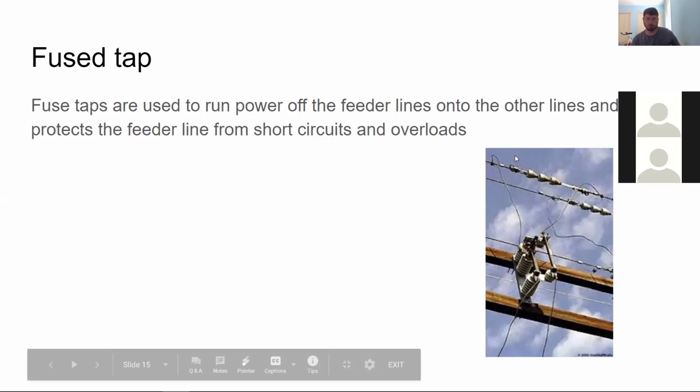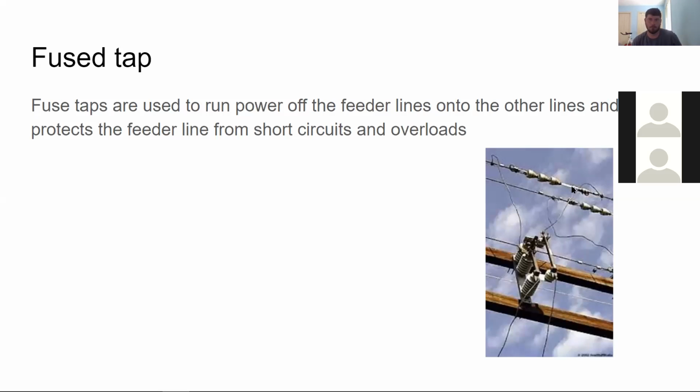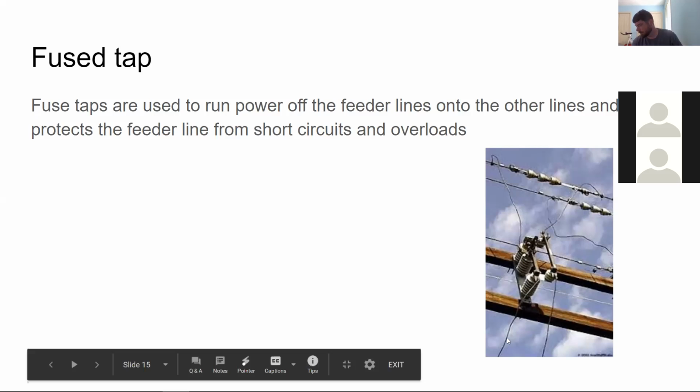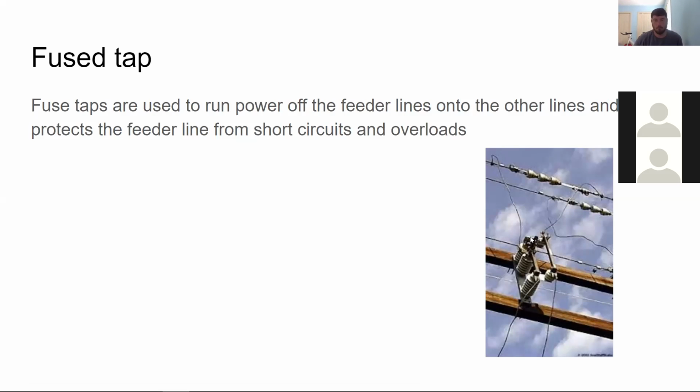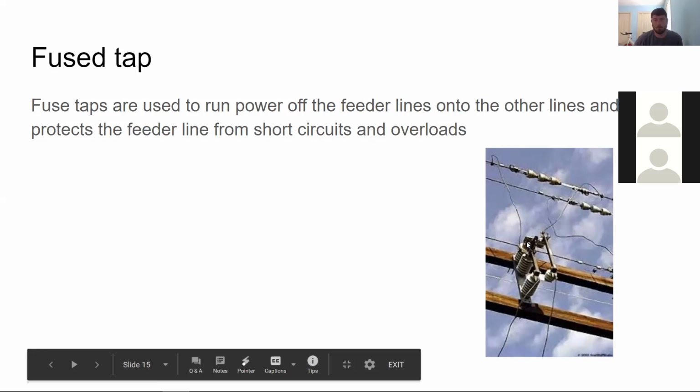You'll notice right here, and this is what they call a flying dead end. Oh, so electricity can't flow anymore. Electricity is not going through this point. They call that a flying dead end. Now, the switch is made in such, and I wish I had a close-up of the switch, that you're able to bypass this without cutting power off. So say if I needed to work on the voltage regulator, you can do an assortment of things with this switch right here to be able to just open one and open the other, still maintain power through here, and work on the regulator without disrupting customers.